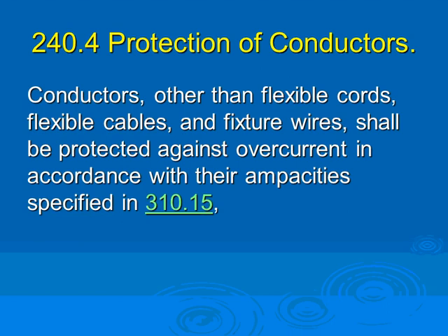What's the exception though? Motors. If you have motors, you have an exception for motors. So I could have a 50 amp fuse tied to a number 14 conductor that feeds a design B motor. And that's completely legit. Why? Because the motors, like you saw yesterday with Kelvin, have an overload protection that protects the motor. And as you protect the motor and limit the current that goes through the motor, you're also limiting the current that's going through the conductor, right?